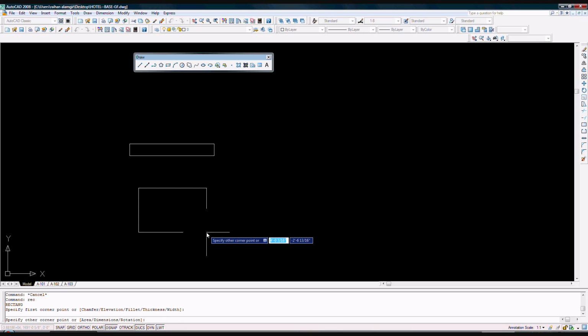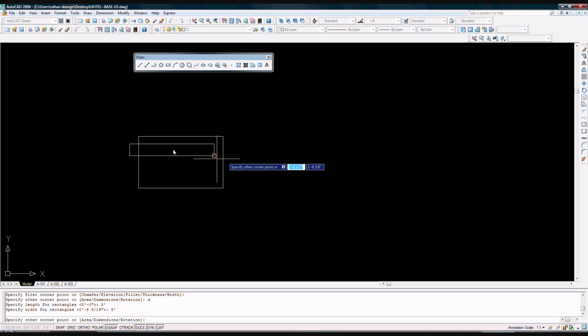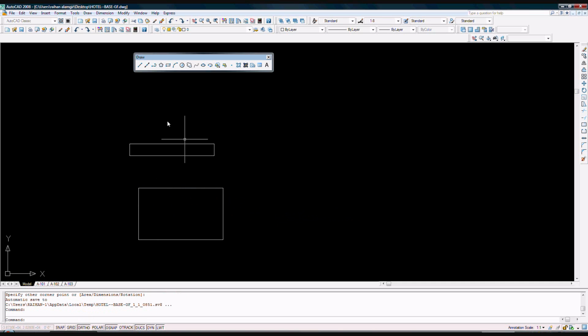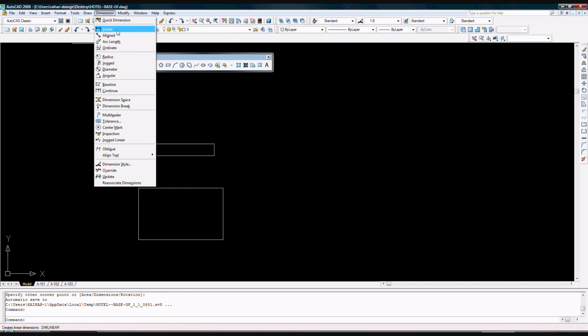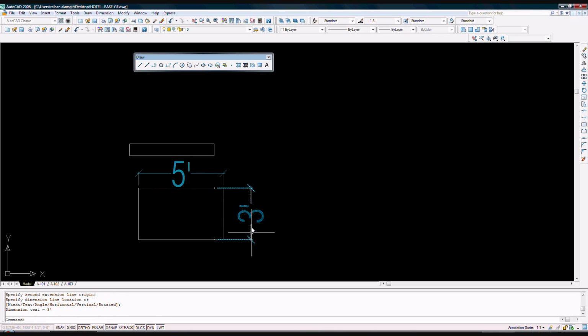The next one is R, enter. First point I selected, I can draw a rectangle with dimension. I press D, enter. For length I want 5 feet, for width I want 3 feet. Enter. So it's a 5 feet by 3 feet rectangle. I can put it in any position, so that becomes the pivot point. So I say I want it here. For the dimension, I want to check whether it's 5 feet by 3 feet, and yes it is.